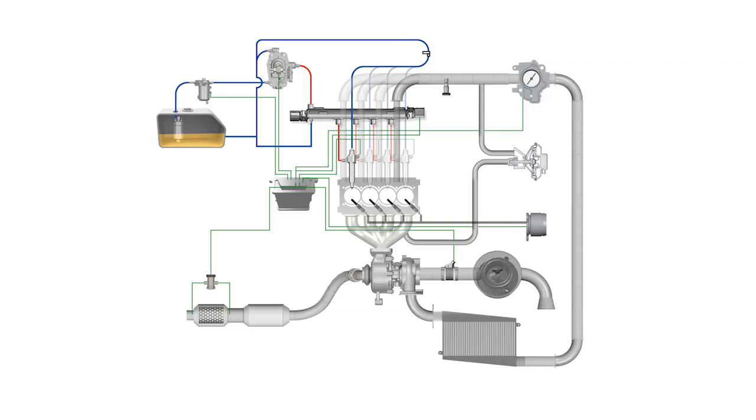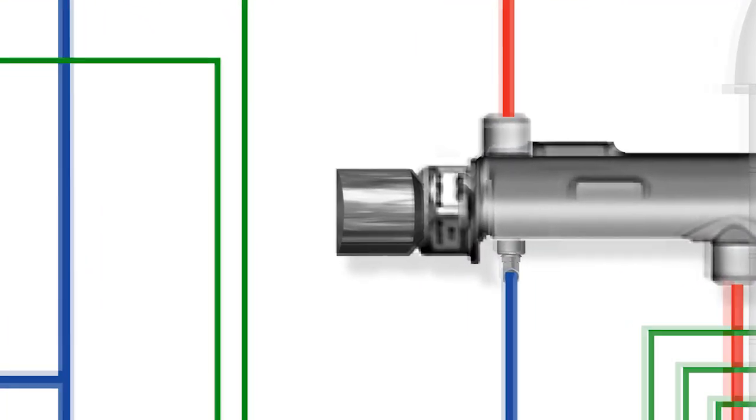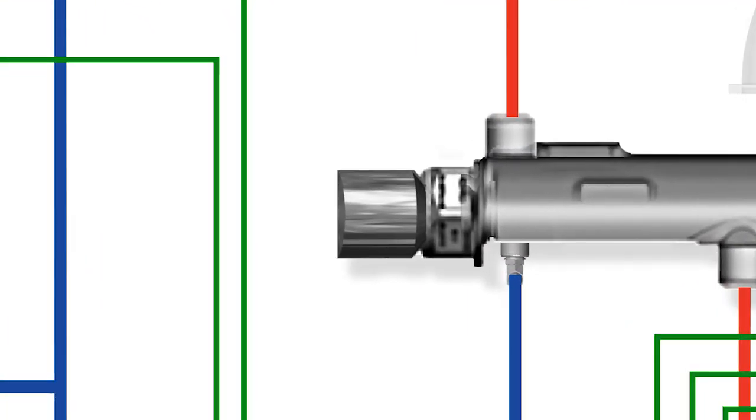If the pressure was at its maximum and the engine was idling, the injector wouldn't be open for very long to deliver the amount of fuel required. This would be hard to control. By reducing the pressure at lower engine speeds, it gives us a longer injection duration, and this is much easier to control.